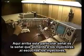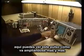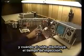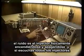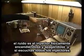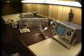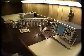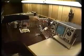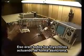If you listen to the injectors, you will hear and see that this pulse width gets larger and larger. And as I'm decreasing it, it would decrease the injector time. The clicking that you hear is the physical injector turning on and off. If you want to listen to all the injectors, that was all four of the injectors firing at a synchronous rate.